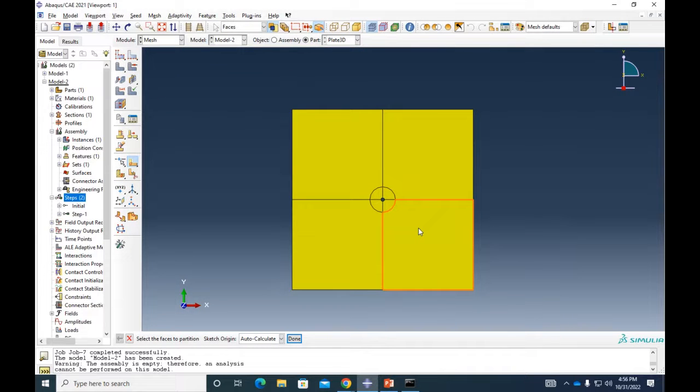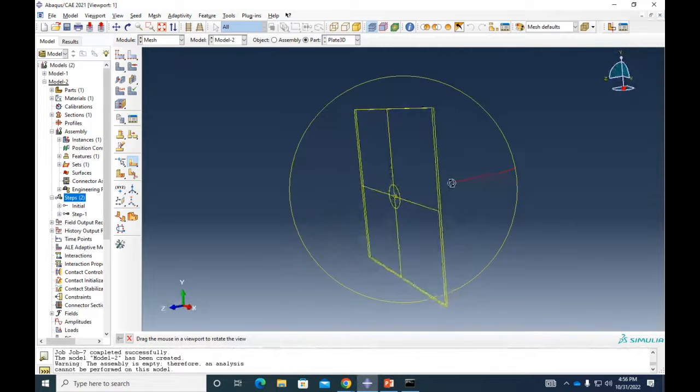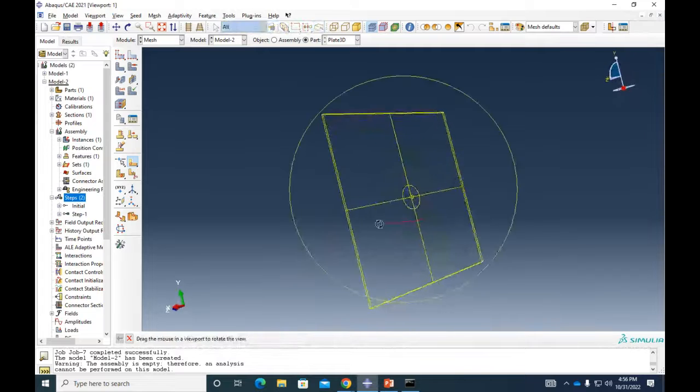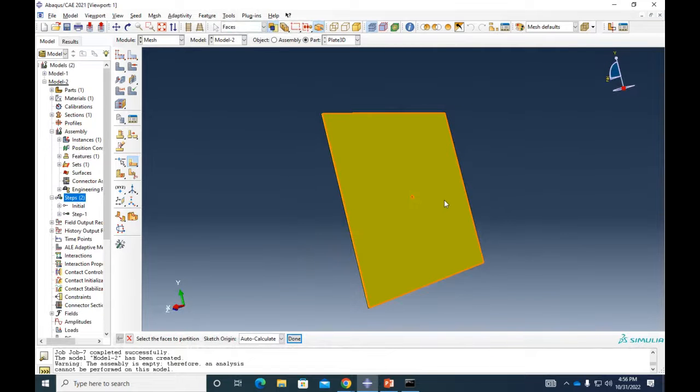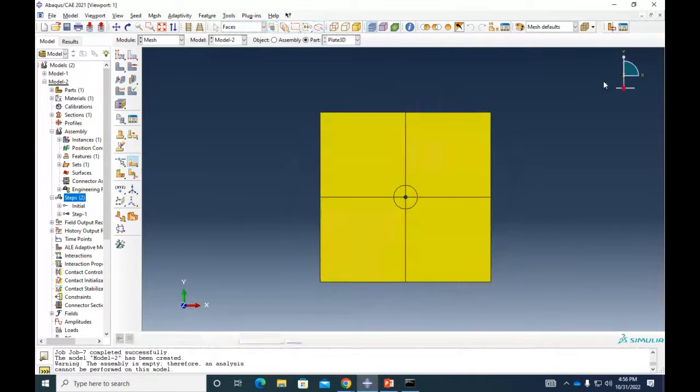Please pay attention to this. I'm gonna rotate the plate. Is the partition on the back? No, that's the complication of 3D. The partitions, you have to extend them throughout the thickness of the plate. All right? So if you add a partition on the other side, does that? No. Doesn't do it? You have to select this partition and extend it. It's like I extrude the partition. That's basically what we're gonna do.